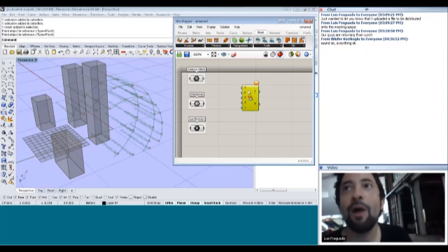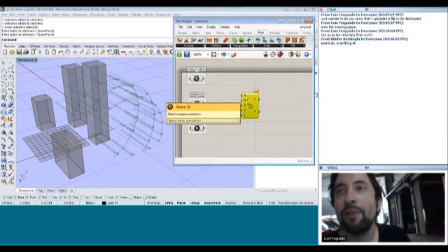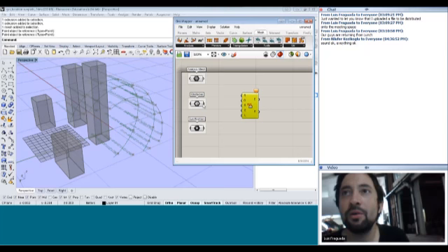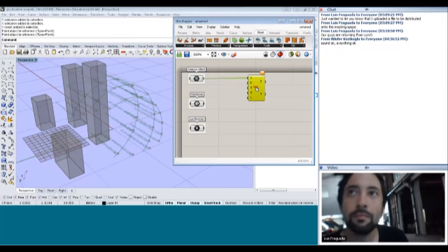So this is in mesh, utility, and all the way at the bottom, exposure. And wow, we got a lot of inputs here. But we'll go one by one. And again, we saw the first day how we can go little by little and just read the inputs. So first of all is our mesh. The mesh we already have, it's this analysis mesh, that's going to go into S. The obstacles are just going to be our obstacles that we've named here.